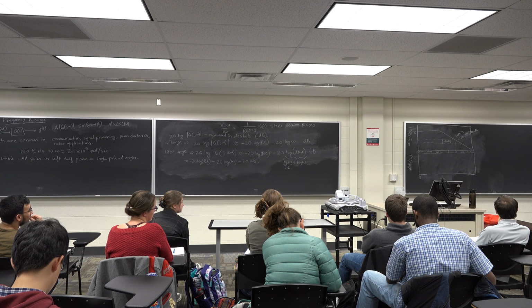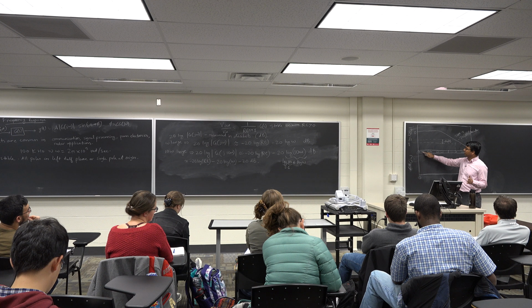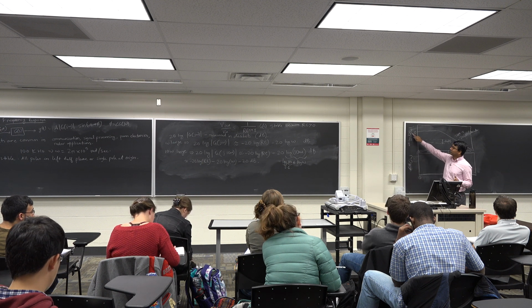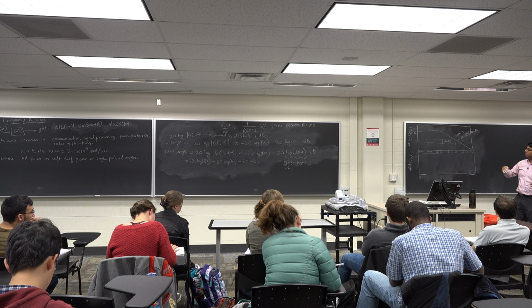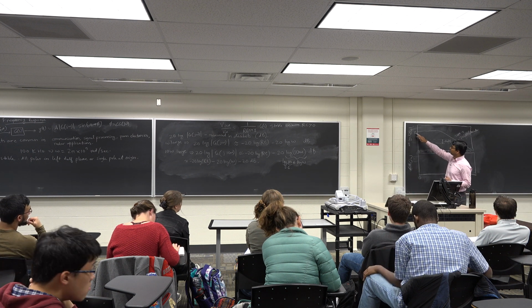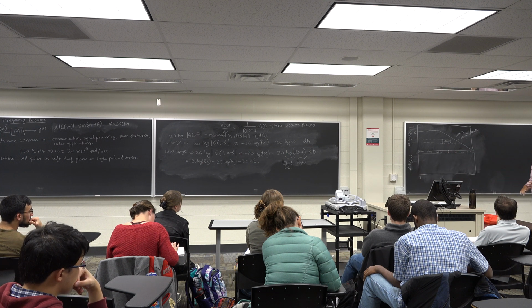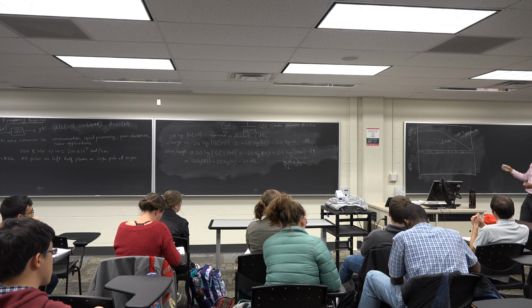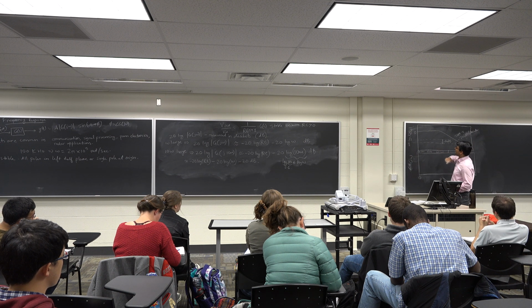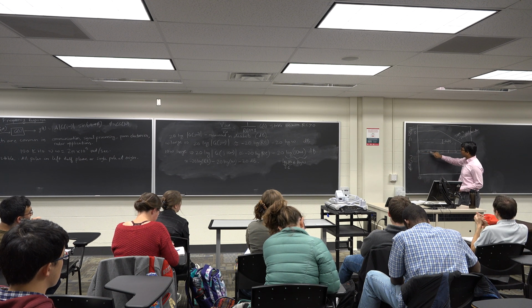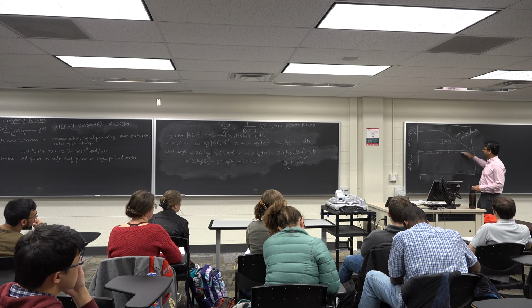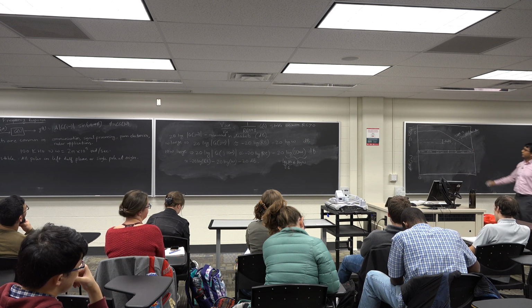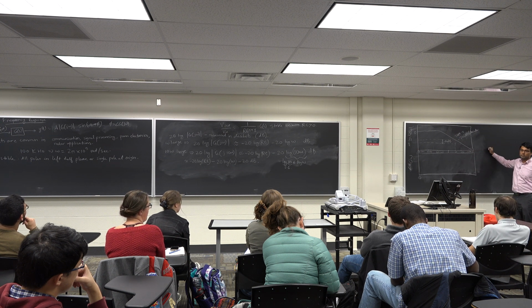So you will put in a sinusoidal wave of frequency 0.001. Well, I'm using frequency, but I really mean omega 0.001. You look at the gain of G(j omega). So let's say your input was sine of 0.001 t, and you look at the output. What's the amplitude of the output? And you plot the 20 log of the amplitude in this log scale graph. So you have a chart paper with this log scale, and you plot this. And you can do it for 0.001, you can do it for 0.01, you can do it for 0.1, and so on, all the way up to omega equals 1000. And then you can draw a curve, and you can look at the slope of this curve.